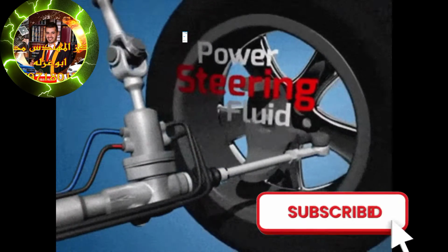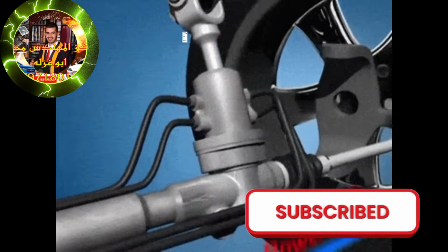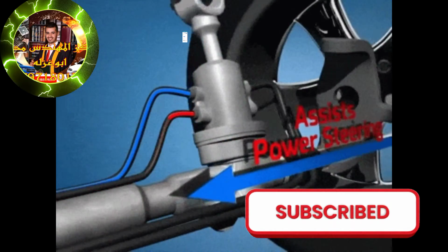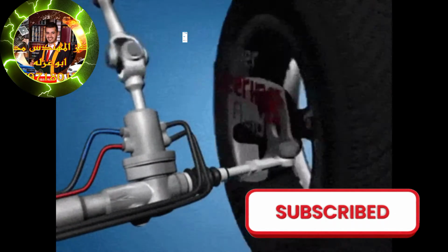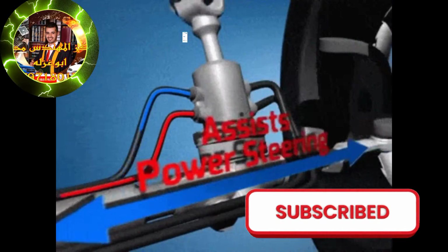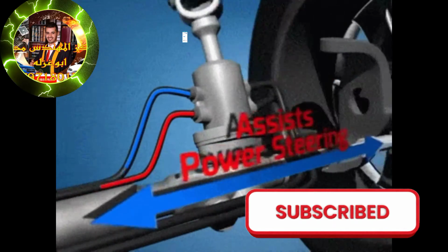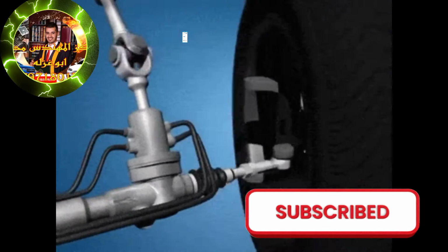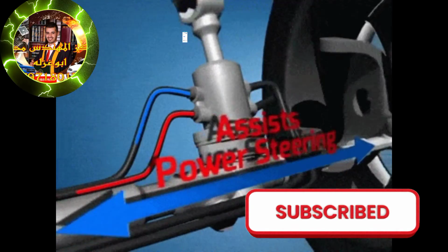Recirculating ball. This type of steering system uses a series of balls and recirculating channels to convert the rotational motion of the steering wheel into linear motion. When the driver turns the steering wheel, it rotates a worm gear connected to a sector gear. The sector gear moves a ball nut, which has ball bearings inside. As the ball nut moves, it pushes or pulls the steering linkage.